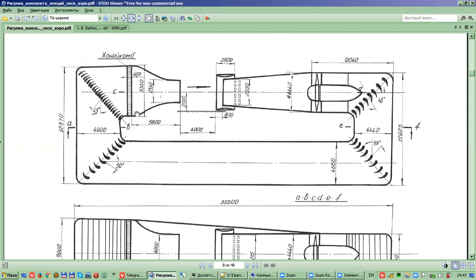And after honeycomb and screens, we have the contraction section. And a very important parameter is the contraction size. This is the ratio of area between this part, the inlet, and this part, the outlet. And this ratio of area gives us a ratio of speed.